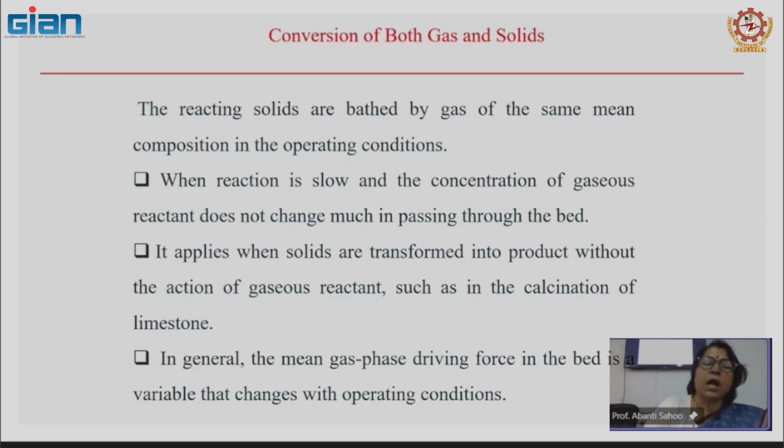Also, the bubble movement takes place so fast that the particles in the fluidized bed, as you may have seen, or in some videos we will be showing in the next class, we can see how fast they are moving. So, with that the reaction will be very little, and the solid or gaseous reactant will not change much; it will just be clouding with the force of the cloud, that is, some wake formation will be there. That means wake formation at the bottom, some W shape will be there, and the cloud will be surrounding the solid particle with the W shape.